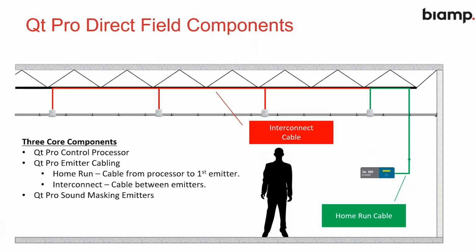All the cables that we use in our systems are category 3 or above. So they're just standard Cat cables. We normally use Cat 5 in Europe, but we can use anything from Cat 3, like I say. The reason Cat 5 is used more is that it's quite flexible, and if we get up to Cat 6 or 7, they can be a bit stiff. We do not need screened cable, just a normal cable, but we do need all 8 conductors on the cable.